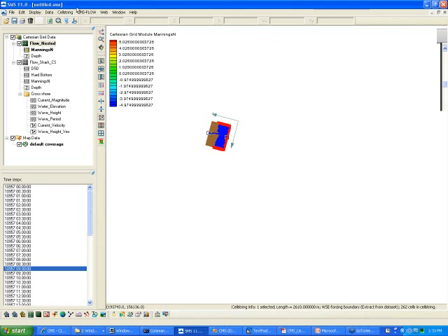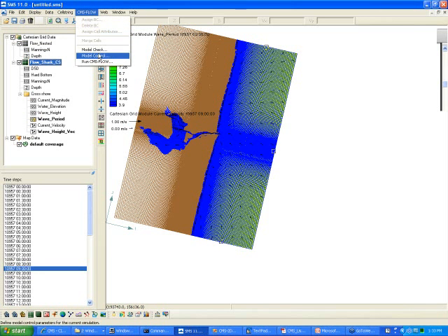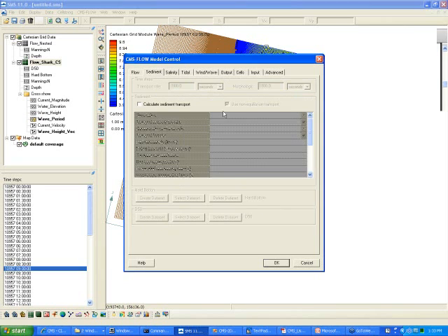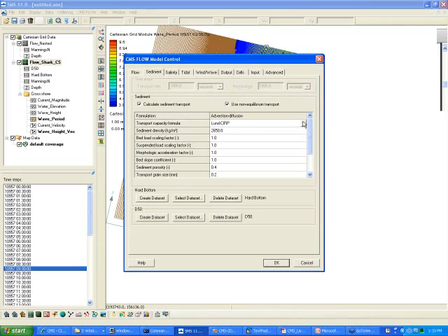And when you're in the interface, this is what I mean by that. If you select the implicit solution scheme, then you're allowed to choose the total load non-equilibrium sediment transport model. Now, the wording in the interface is not the greatest, but we're changing that for the next SMS interface.